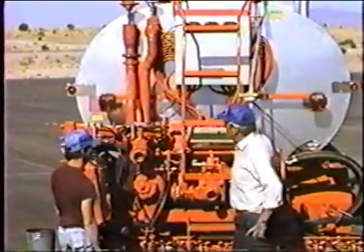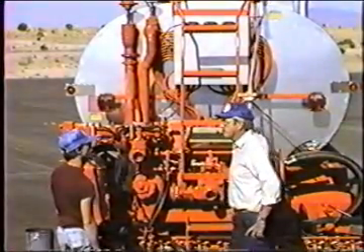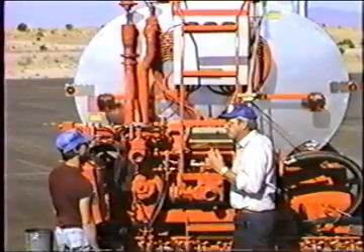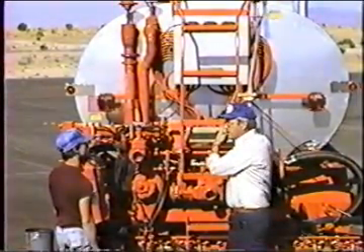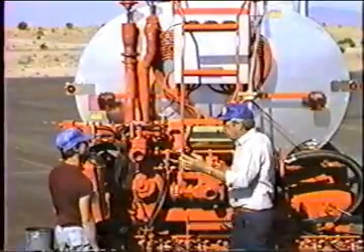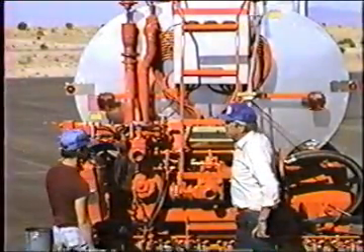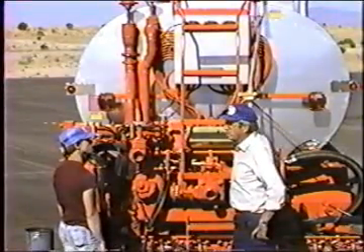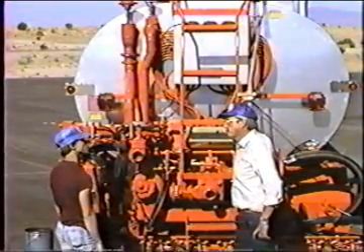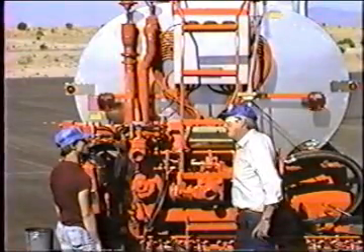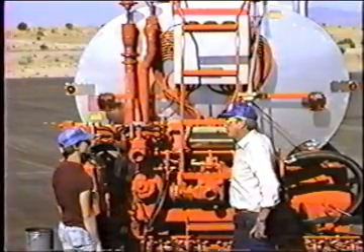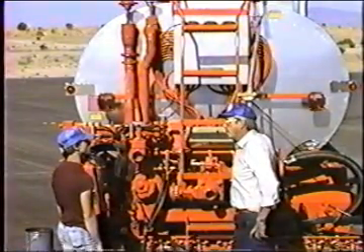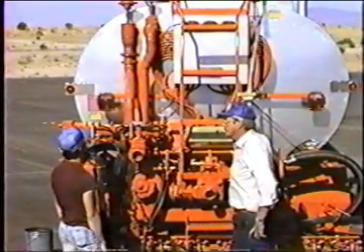Typically we would load the truck with hot material and go to the job, or the material that comes to the job and transports is heated. It's in an insulated tank like this, and it'll still be hot. We load it and we spread it. Sometimes it's been in the truck too long or in the tank trailer too long and it's cooled down. Say we're shooting an emulsified asphalt and it arrives at the job at 100 degrees. Well, we want to spread that material at about 160 or 170 degrees, so we would heat on it for an hour in order to get it up to that temperature, raising it 100 degrees.